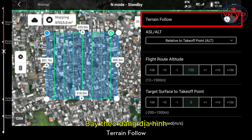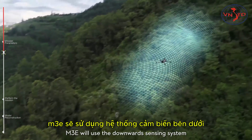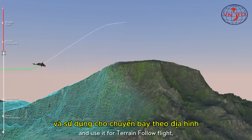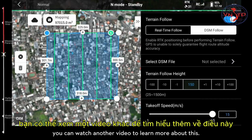Terrain follow. Real-time follow. By selecting the real-time follow, M3E will use the downward sensing system to capture the terrain data and use it for terrain follow flight, while keeping enough data accuracy and overlap ratios. You can watch another video to learn more about this.